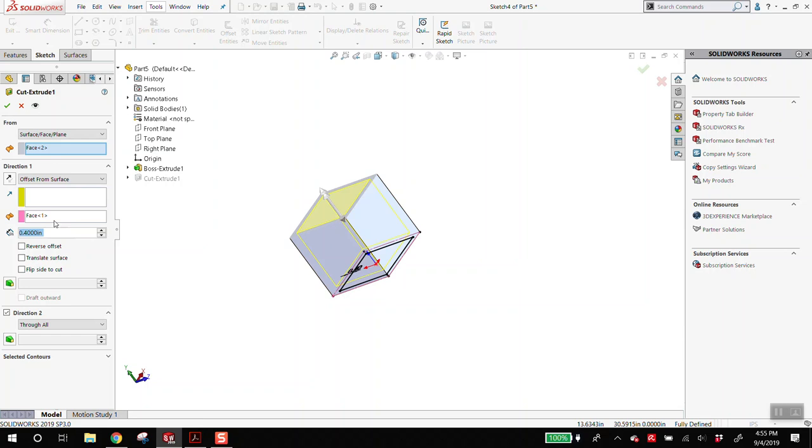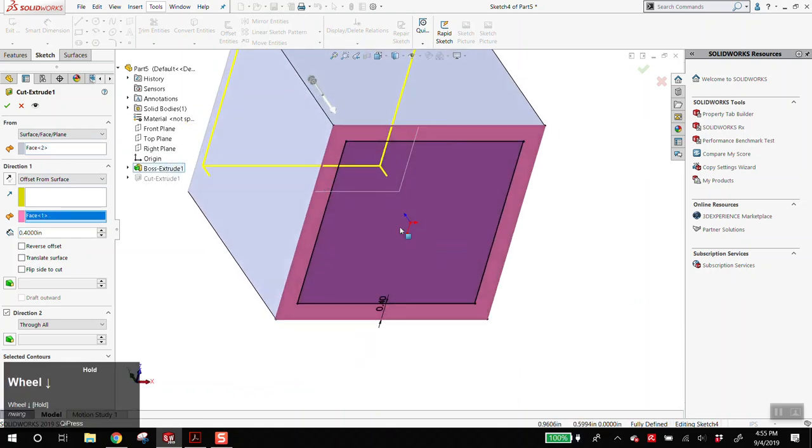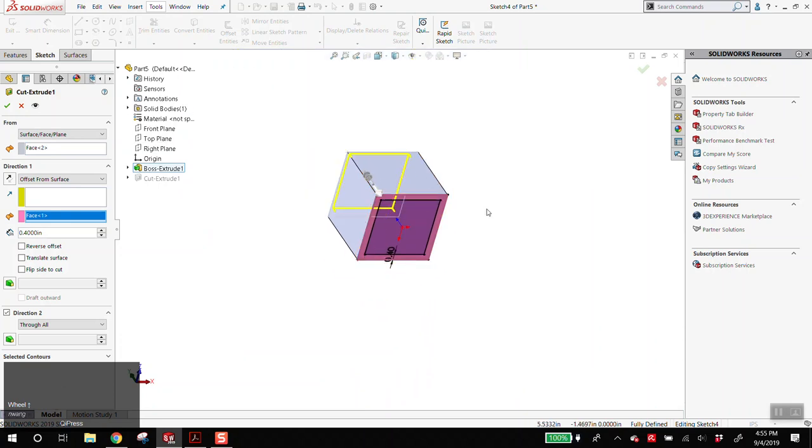If it says the end face cannot terminate the extruded feature, chances are that the face you selected is not in the direction the cut is going. So you want to go back to this portion here and click on it so it's blue, and make sure that you're clicking on the bottom face. Or you can click on the top plane. Is that working? The arrow should go like this is the arrow, right? So you're going from,